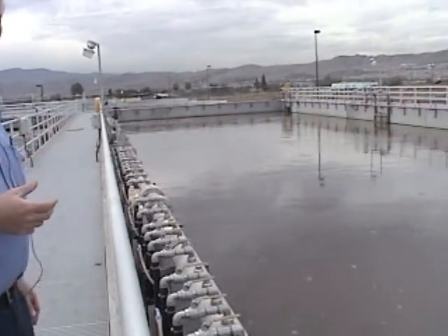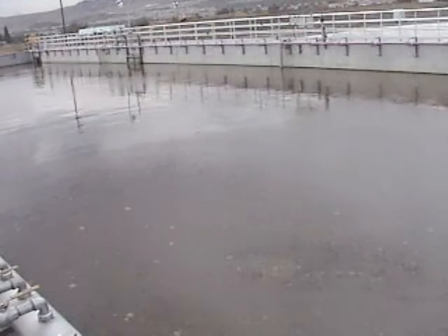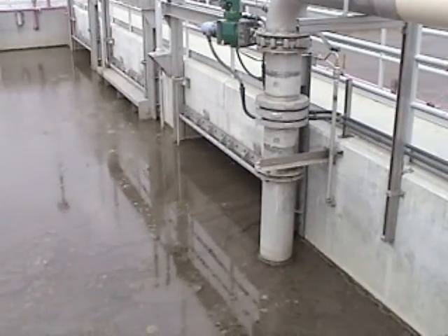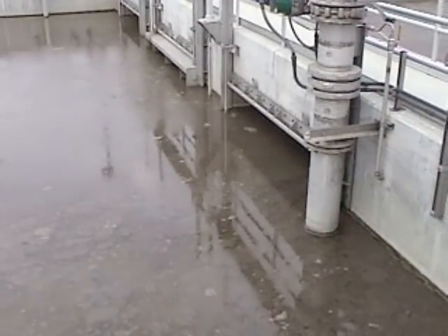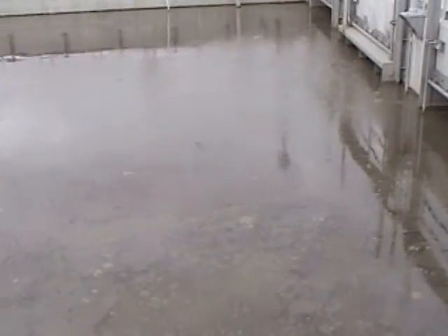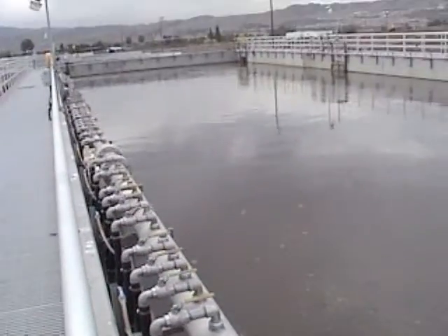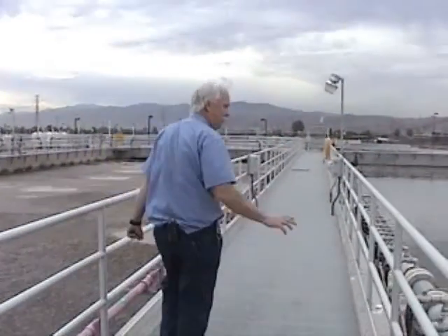What we found here at RP5 is the blowers are very large, and we actually were over aerating. To get our TINs down, we had to drop the DO, so we have huge anoxic zones. So at the flows and the loading that we currently have, we have these air panels isolated. As the flow increases, we'll probably have to bring these panels online. These panels right here, you'll see these all around the basins.